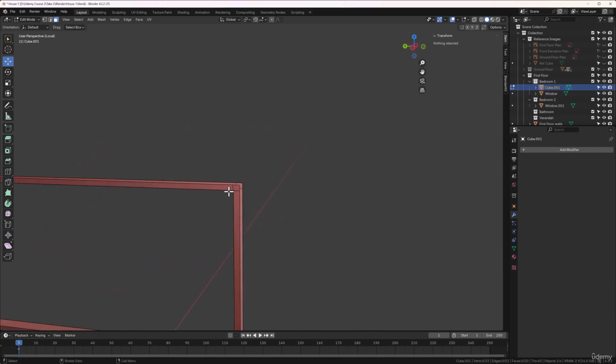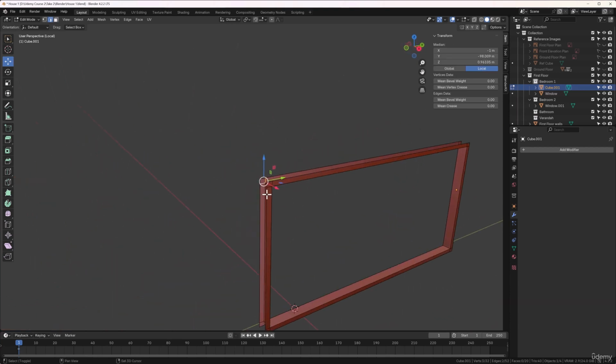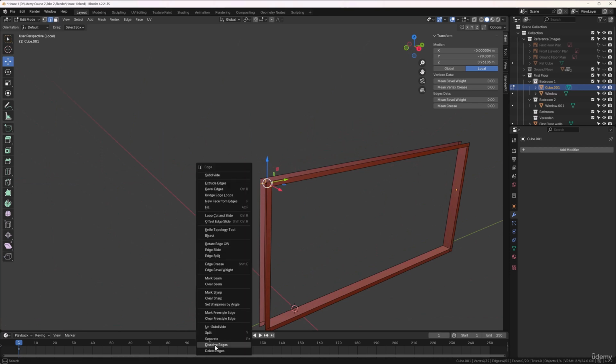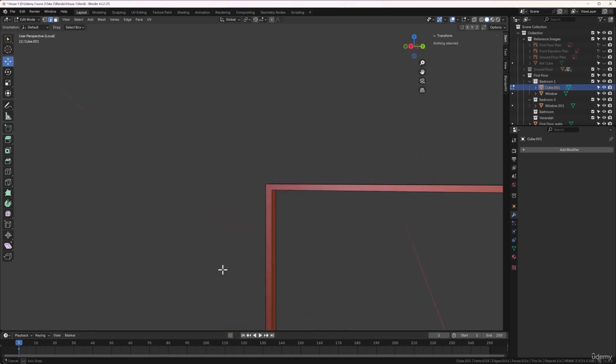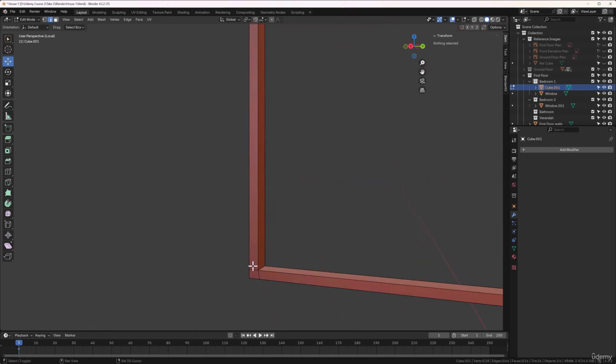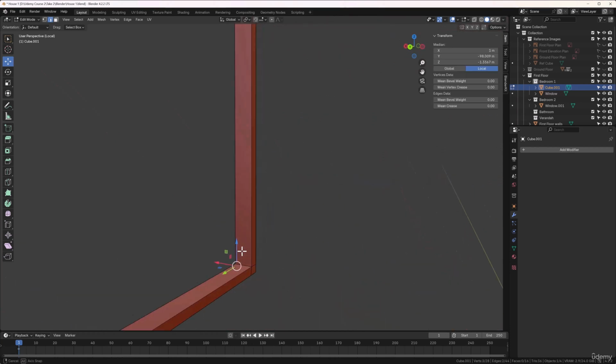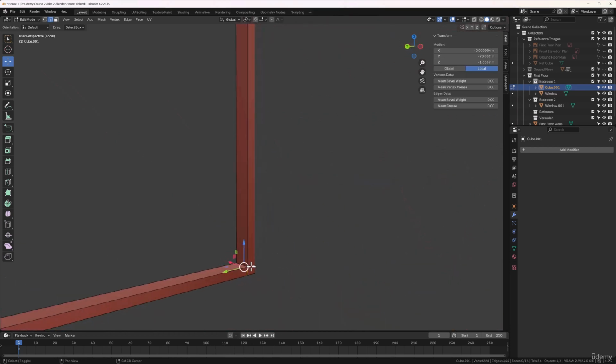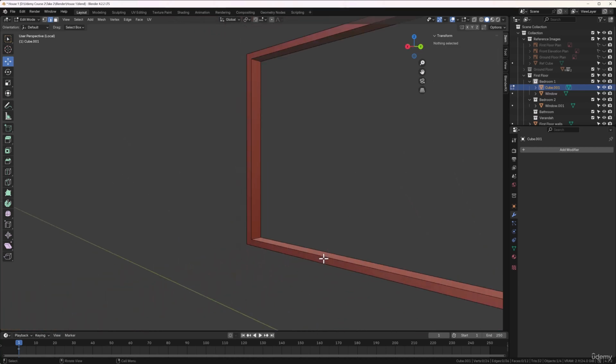And now let's select edges, so I'll press 2, and let's just grab some of these edges. And I don't know if we'll be able to dissolve all these surplus edges, but we'll give it a go. So let's grab those ones, right click and dissolve edges. And yeah, we can do those. We may not be able to dissolve all of them, we'll see. Let's grab those 4 there and right click and dissolve edges. And that's alright.